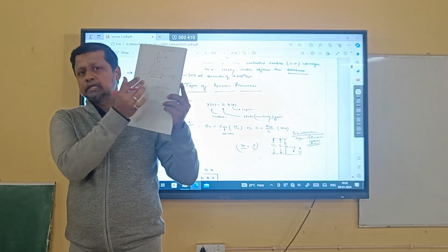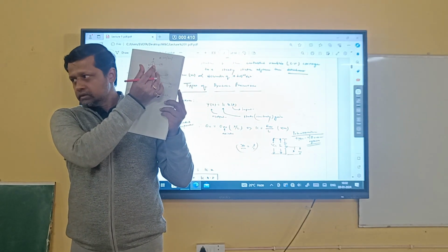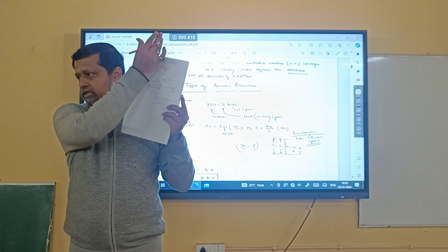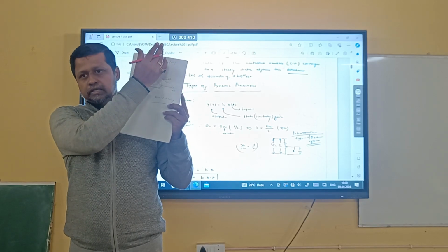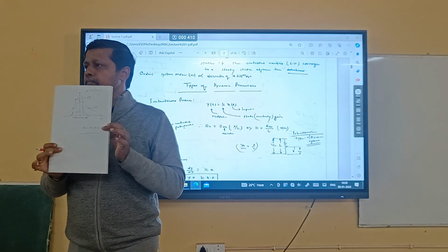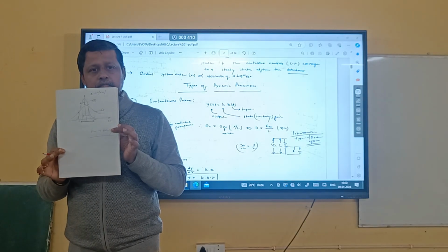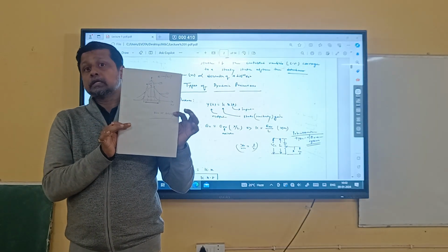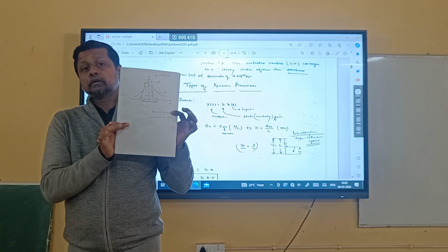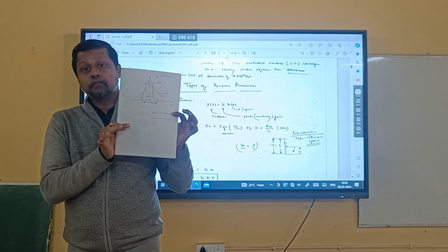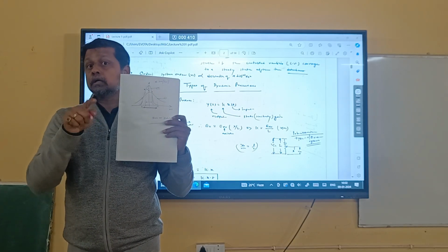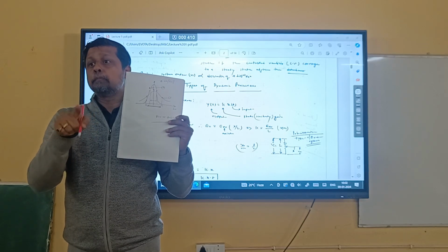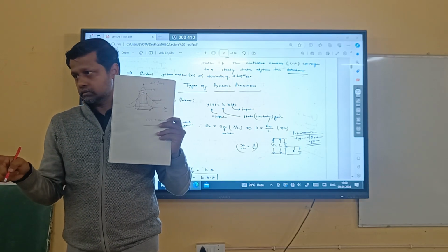So on a frequency plane, it is something like that. You have compressed the plane. Okay? So you increase the strength of the signal. You increased the Q factor, the gain improved, bandwidth decreases. But in the original characteristic, it offers wider bandwidth, therefore a more stable system. But for that, you need to compromise with the gain.